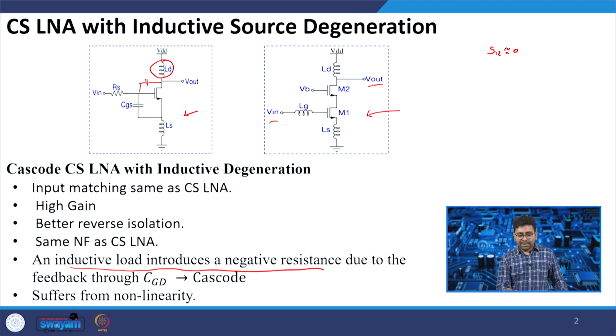If the isolation between output and input is better, you can consider it more unilateral. While designing this structure, you can also use the S parameter method by dividing it into two ports, and based on whatever S parameters are available, you can find the input and output matching networks.